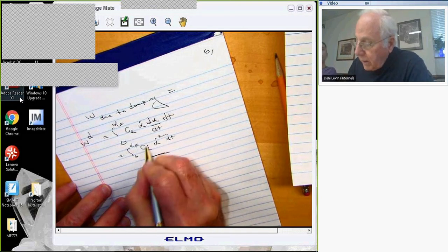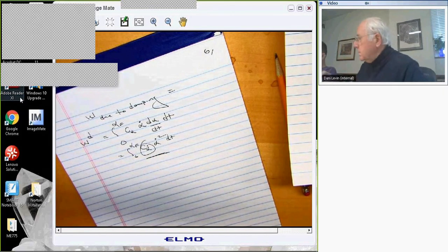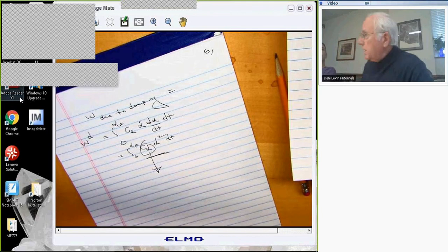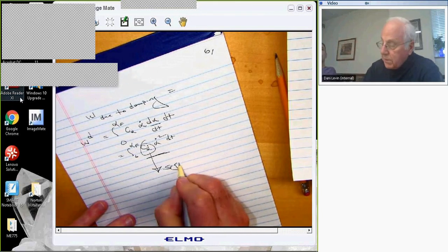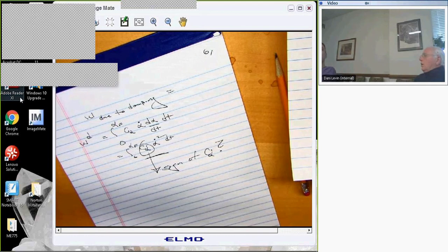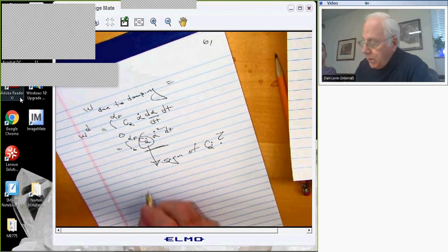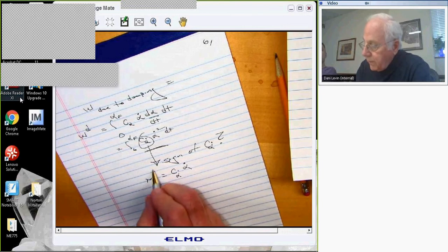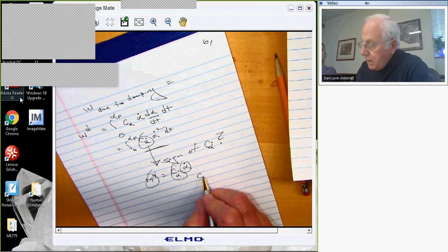So what do I know? Well, if this is a positive coefficient, which it is for most models. What? That's not true. Yeah, well, what is that coefficient? Is it positive or negative? What is the sign? Well, we want the moment to resist the motion, right? We want the damping moment to oppose the motion, to be in the opposite direction of alpha dot. So if we say M damping is C alpha dot, and this is to be in the opposite direction of that, then C must be less than 0.